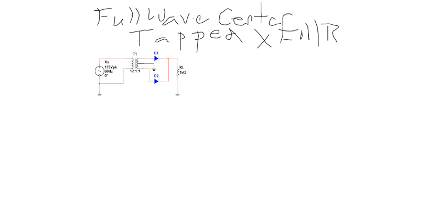Now, this is still a 6-to-1 transformer. What it's saying is if I have 12, let me get my pointer out here for a minute. If I have 12 turns here, one turn on the bottom half and one turn on the top half, if we didn't connect the center tap to anything, then that would be a 12-to-2, which is the same thing as a 6-to-1 transformer.